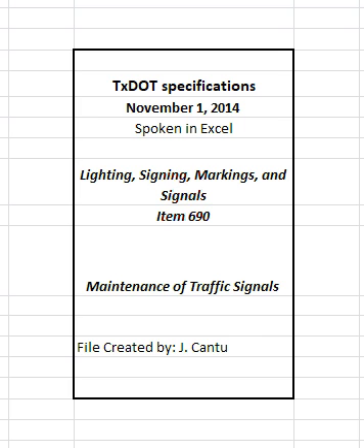4.12 Traffic signal controller cabinet, ground mount. Install, repair, replace, remove, or modify ground-mounted cabinet. Plumb and tighten the cabinet. Apply silicone sealant around the base of the cabinet. Coil all cabling that enters the cabinet neatly on the cabinet floor. Mark and terminate each cable as shown on the plans, or as directed.